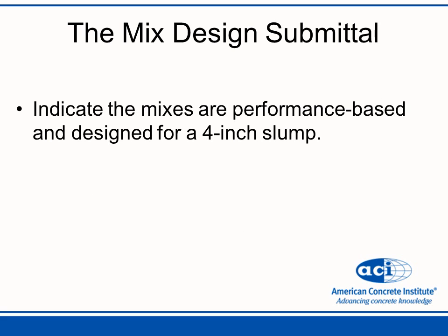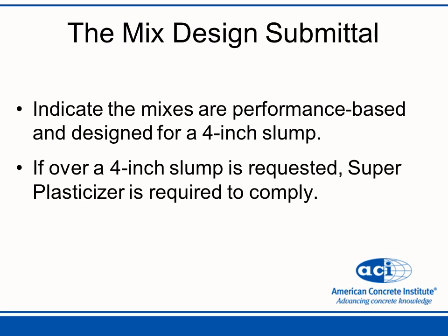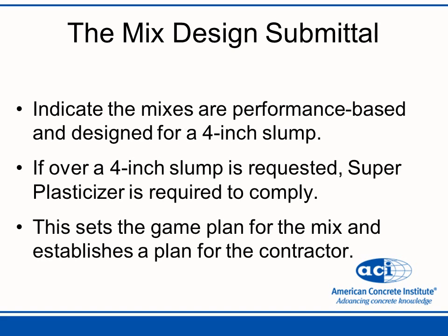The submittal should indicate if the mixes are performance-based and designed, say, for a 4-inch slump. And if a 4-inch slump is requested, superplasticizer can be added to increase the slump of the concrete. And this submittal will set the game plan for the mix and establish a plan for the concrete contractor.